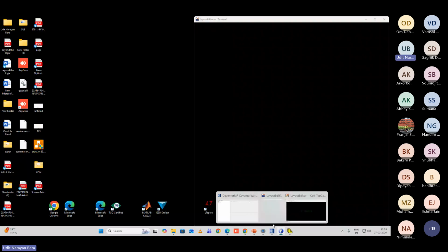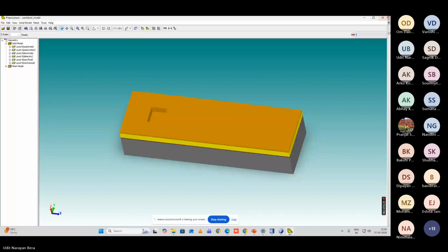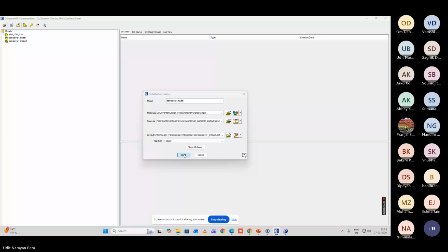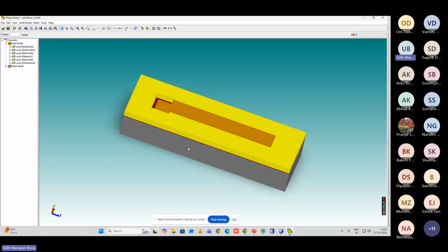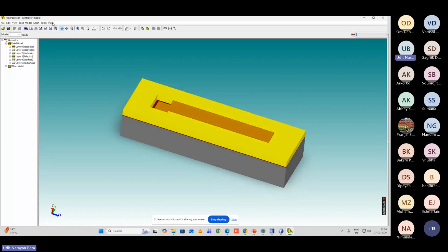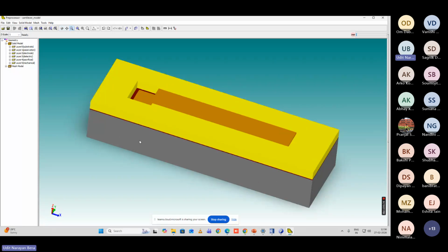If I rebuild it, yes, see, after make zero, I mean, after that mask, this yellow portion is your polyimide that will be etched away later. But now you can see your cantilever is already grown on top of that sacrificial layer, and one portion is already fixed. That's your cantilever. So what will be the next step?